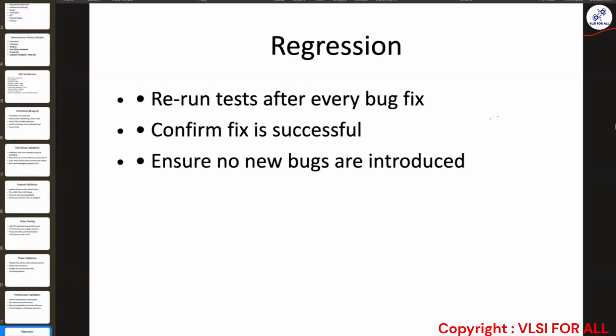Then consider you are seeing an issue where the enumeration is not happening. Okay, so you capture the relevant logs for it, but before that you may have to look at other scenarios also. In which scenario, in the S0 state, meaning up and running state, is the enumeration having a problem, or does the issue happen only in corner cases?